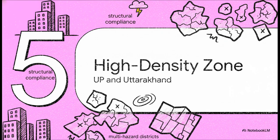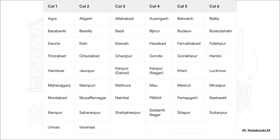Moving to Section 5, High-density hazard zone, which includes UP and Uttarakhand. Just look at the sheer volume of districts across UP and Uttarakhand. This requires monumental compliance, spanning incredibly diverse terrain from the plains right up to the foothills. Operating anywhere within this dense list means multi-hazard compliance is your daily baseline. It also means that routine maintenance steps are absolutely vital. We're talking about scheduling regular non-destructive testing on concrete structures, especially post-seismic events, to continually verify that the embedded reinforcement integrity is actually holding up over the decades.